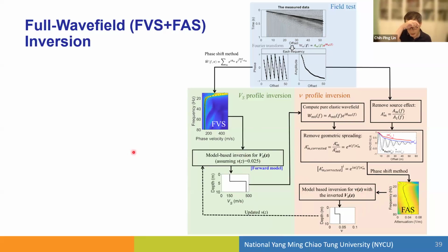I don't think I have much time, but basically what we have done is not only work on onshore land surveys, we have extended the approach to offshore and also air-coupled. Offshore mostly means they use an air gun and hydrophone, so we have to model the explosive source, and we can model not only displacement but also the acoustic wave.